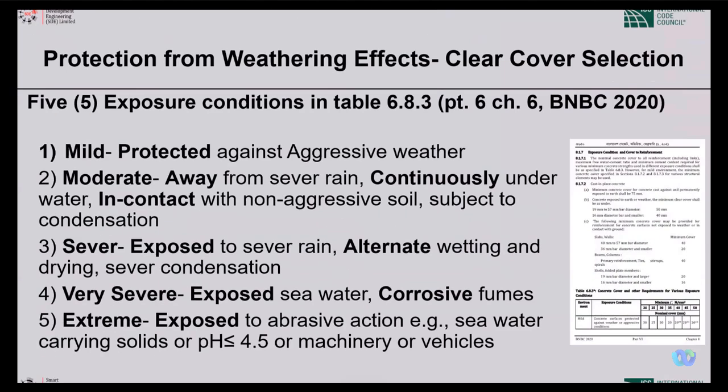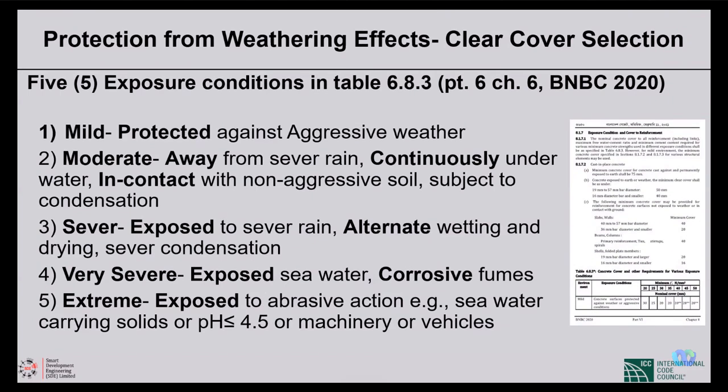Okay, now protection from weathering effects, clear covers. So BNBC in their article 6.8.3 in part 6 of chapter 6 discusses providing the clear cover from the weathering actions. So they have described five different exposure conditions which need to be considered during the decision making process of selecting the clear cover for a structure, like mild,